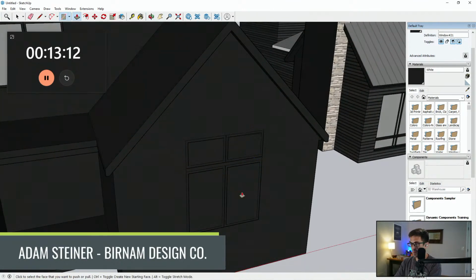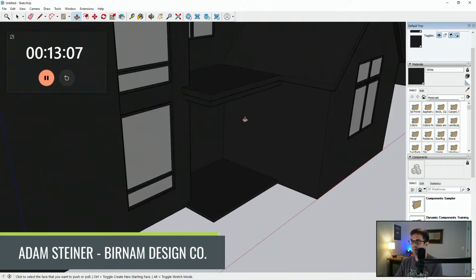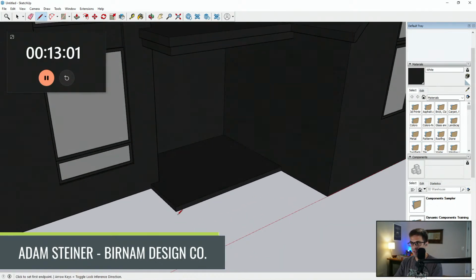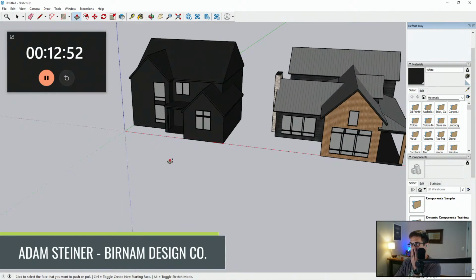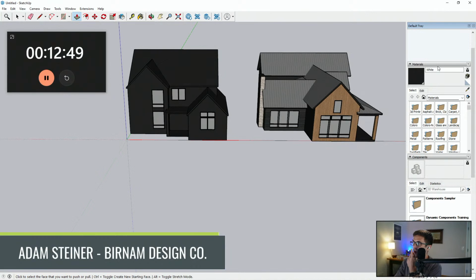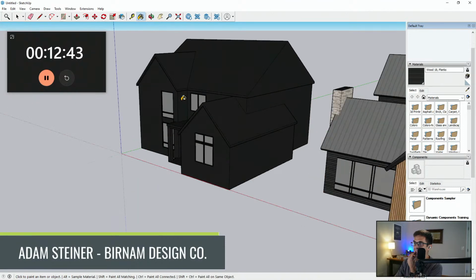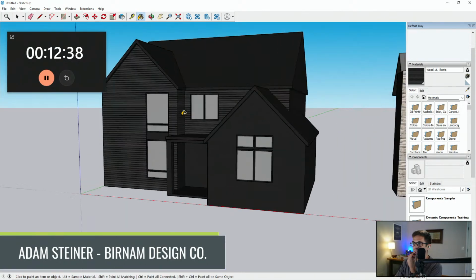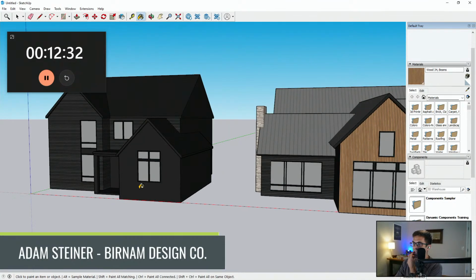Okay. Let's bring this porch out a skosh. Just proportionally, I feel like it needs a little more presence toward the front. Let's show a 12 by 12 column on this front corner. Push and then control kind of creates a new element there. And for all of these cabin ones, I've been showing very similar materials, because I like it and it's been fun for me to show that consistent throughout. So I'm going to keep doing it. Nobody has stopped me yet.